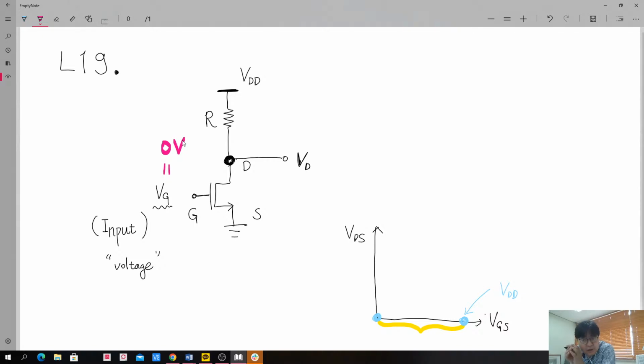Now, transistor. So in this case, ID is just given as 0. Although I use this approximation symbol, you know that this is almost 0, so we can safely say that this is just equality in our engineering sense. So simply speaking, when we just set our gate bias as 0 volt, then this transistor does not conduct at all.